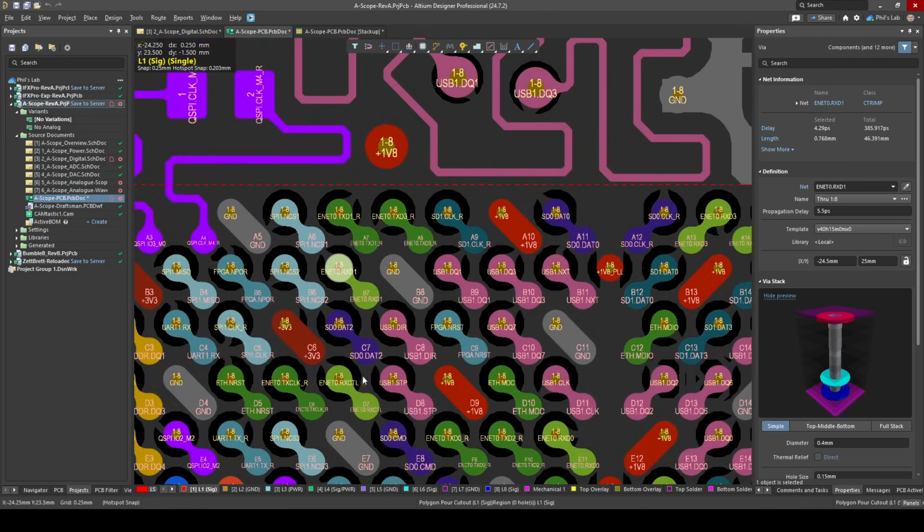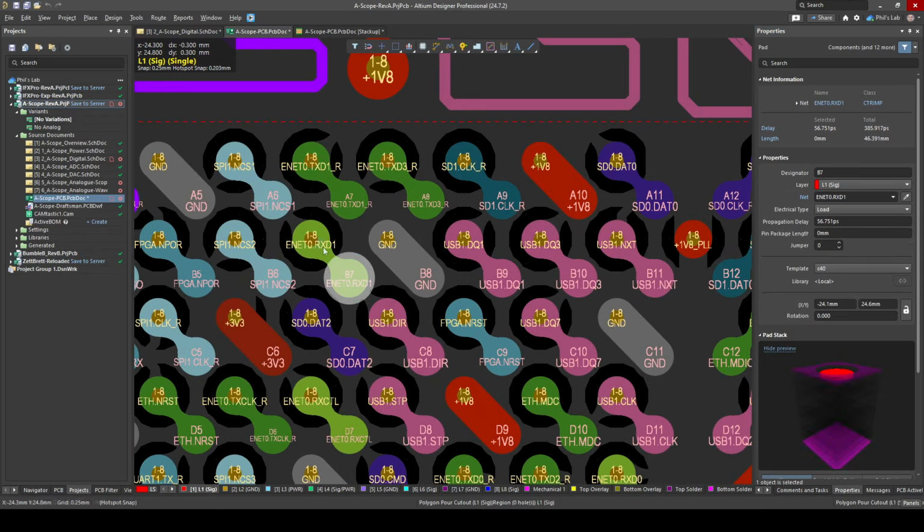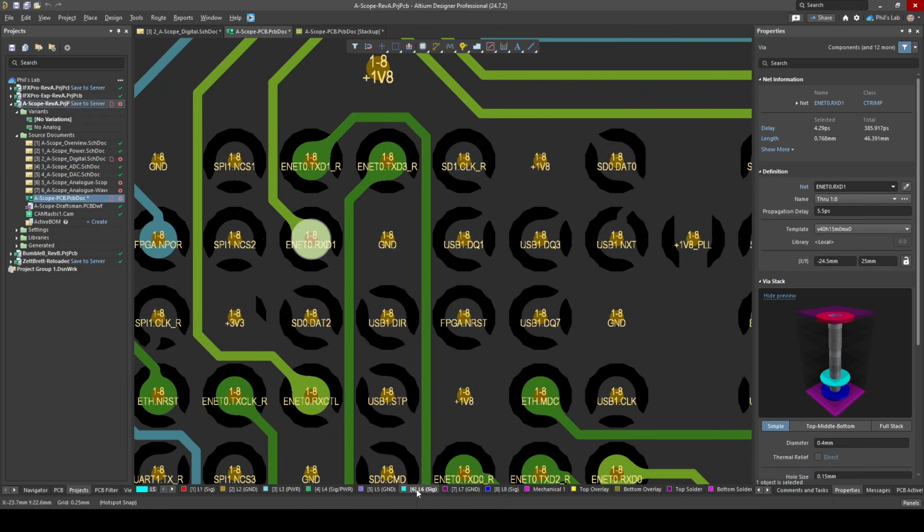Normally, my trace widths for these controlled impedance traces are, of course, set to a 50 ohm controlled impedance, which is a width of 0.12 millimeters. It depends on whatever stack up and impedances you require in your design. So from a pad into the via, drop down to layer 6. Layer 6 I chose again because it's a stripline.